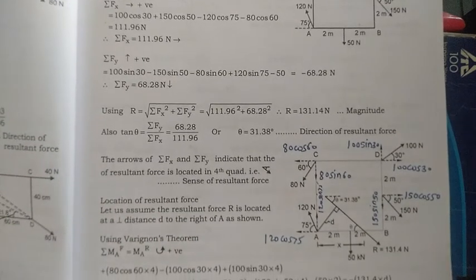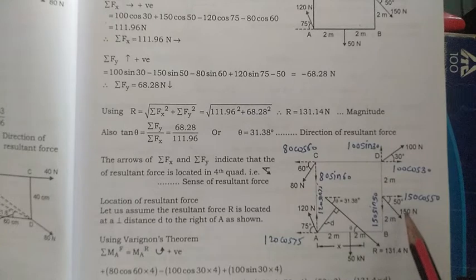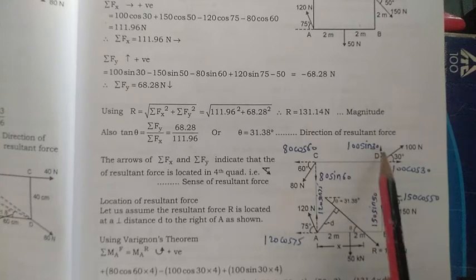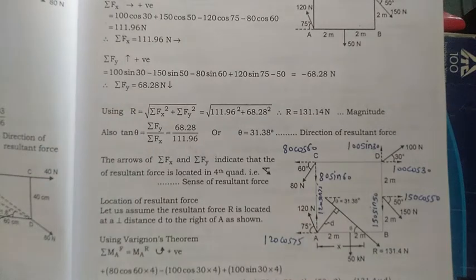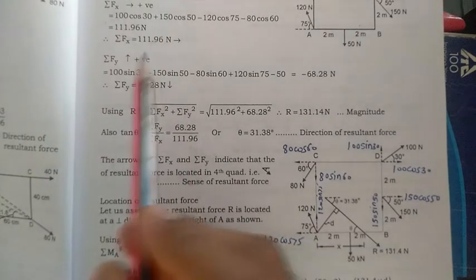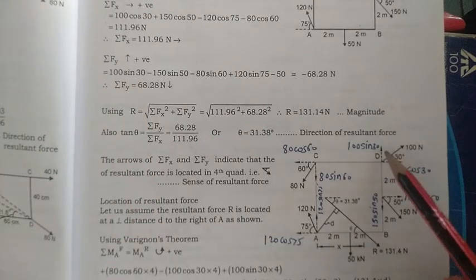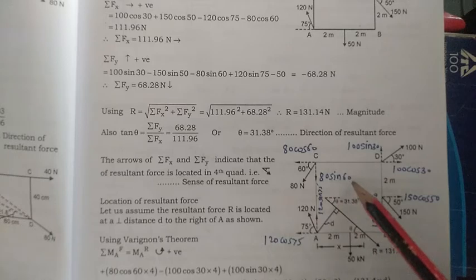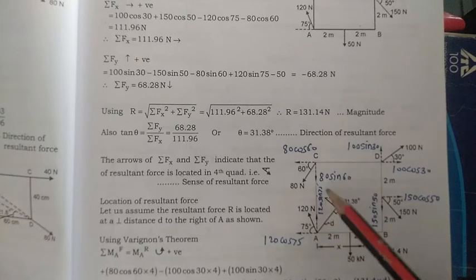Now in the next step you have to get the summation of all the vertical forces. Let us consider the first one, 100 sin 30, running vertically in the upward direction. Consider this force as positive. Apart from this one, the next force is 80 sin 60 vertically in the downward direction, so give the minus sign for this one. The next force is 120 sin 45, in the vertical direction, so give the plus sign for this one.